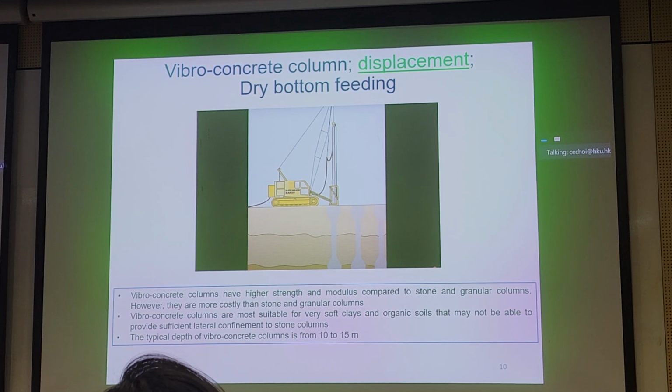This technique is very good for cohesive and fine-grained soils. You might not find this so good for granular material. You can imagine that concrete doesn't set right away. So if you have your borehole collapsing, you have granular material collapsing into it, you're not going to get a nice vertical concrete column. So those are the advantages and limitations with vibro concrete columns.